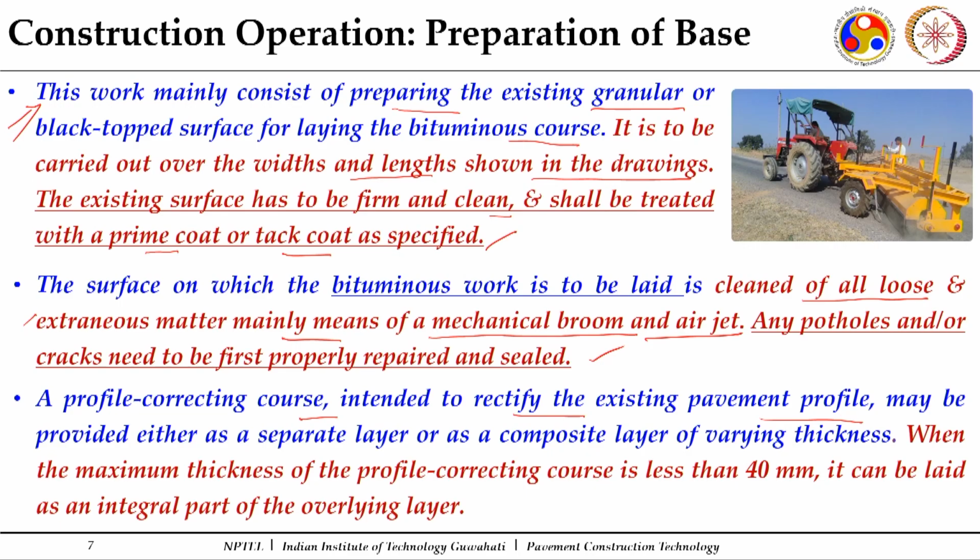Say I am going for a wearing course of a thickness of 40 mm, and in certain cases there may be upheavals of 20 mm, depressions of 20 mm, then at some place the layer thickness, when I am going to meet the drawings... So, if the existing surface is like this and I need to maintain a profile, it may happen in this manner: at one place the thickness may be more, at another place the thickness may be less, whereas I need to have the uniform thickness which has been designed.